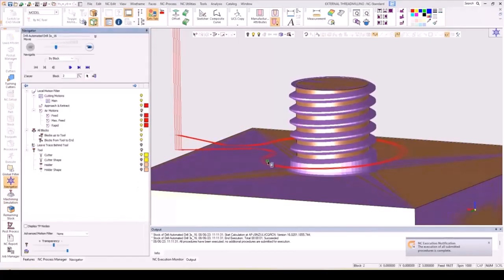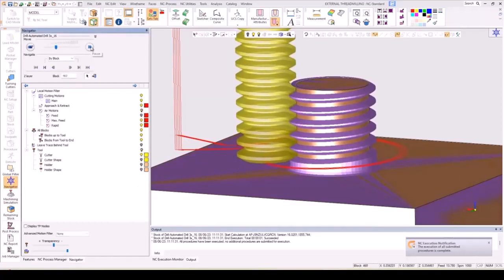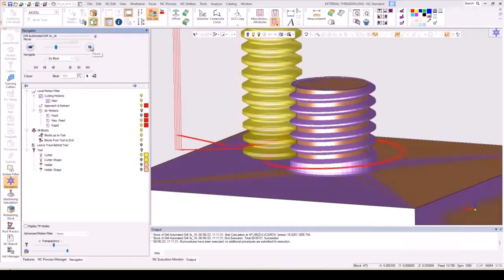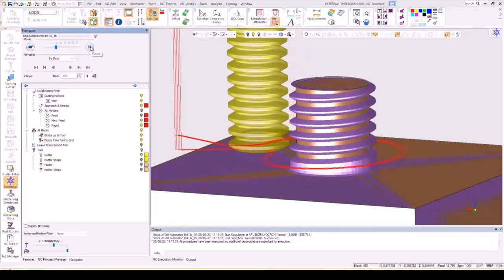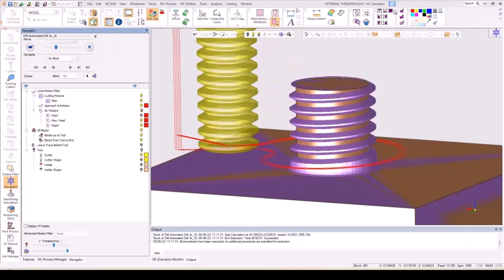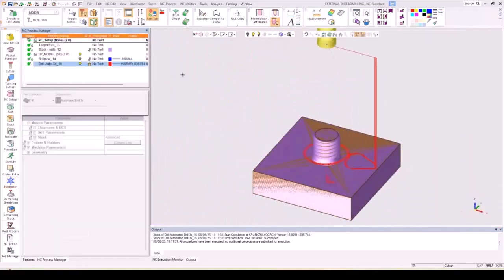So we're taking 5 passes. It's machining its way around. And we get a good result. So external thread milling, that's how you set that up. And again, guys, we'll have these files available. So should you want any of these as just a sample for setup or anything like that, they'll be available to you.